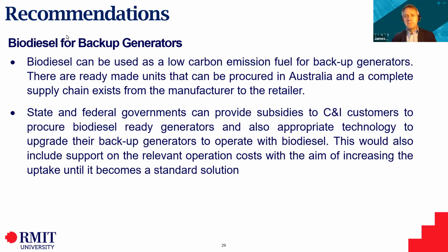Thanks, Mahdi, and thanks, Bani, for the question. Who'd like to tackle Peter's question about whether the backup generators incorporated a voltage droop or other reactive compensation to mitigate the voltage rise? Yes, we use a voltage droop type control here, but it is slightly different because we also have an integral function to correct the voltage back to its nominal value.